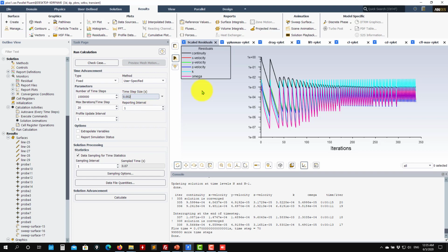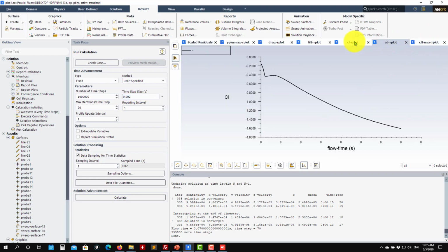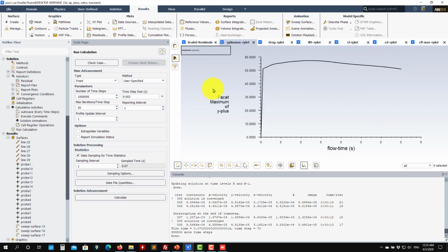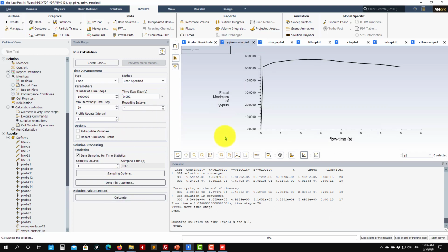Now I will see a jump here, but also in all my quantities, due to the fact that we're increasing the time step, and it also is likely that it will take longer to converge. However, see that now you will advance much faster. So this will be a compromise. If you want accuracy or you want to go fast, this is something that you can do because we are on URANS. There is no problem, unless this is something very delicate, and unless you should have a single time step, you shouldn't play with your time step. So let's go calculate now.